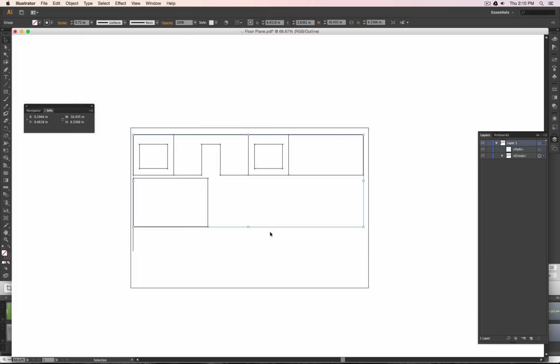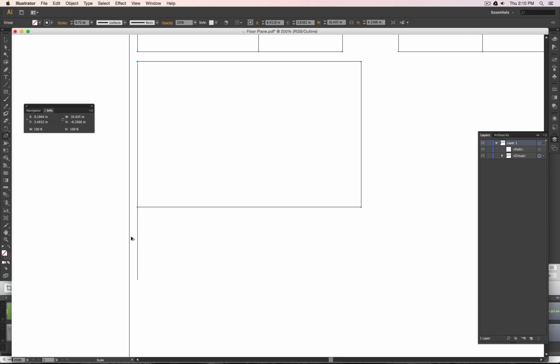Okay, let's do this one more time. So I click this whole group, press S, then you see there is a magenta, a cyan small cross. I can move this one and snap to that point. And here click and with shift pressed move this one down till it actually snaps to the end of this line.